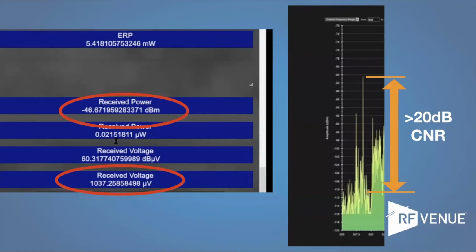So if you use our Vantage program, you can set a threshold. Taking one of these orange lines that I've got at the bottom there, you can drag it up and down. And so I like to set that threshold 20 or 25 dB above my noise floor. And as long as the signal from a radio transmitter, the little skinny lines, is above that line, I'm pretty good.